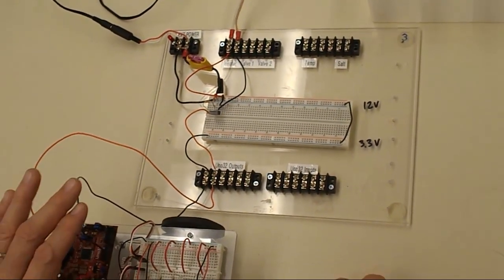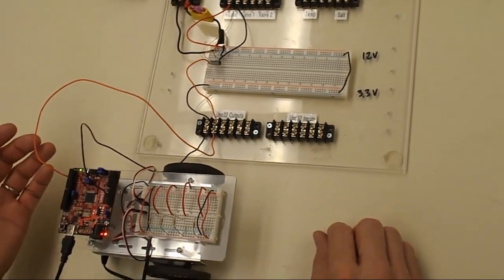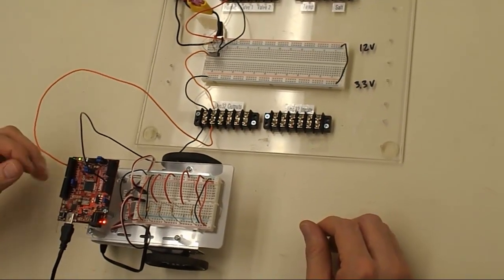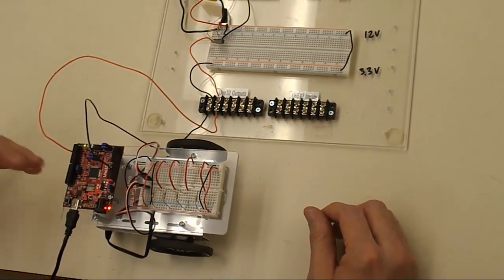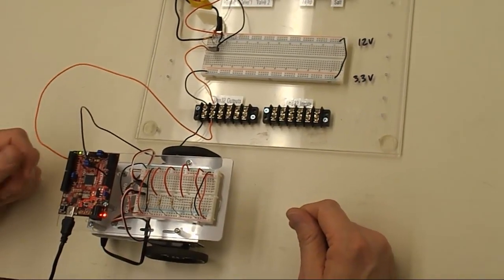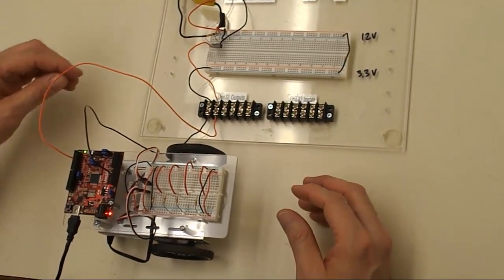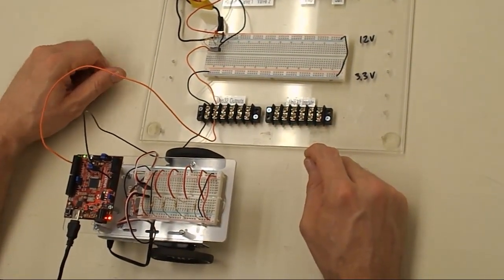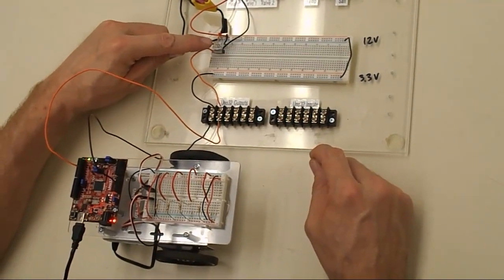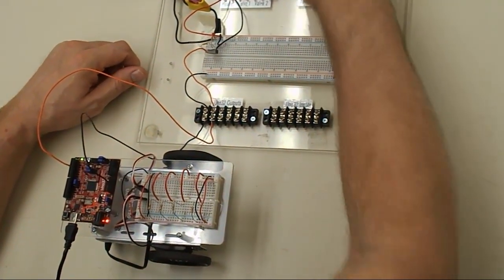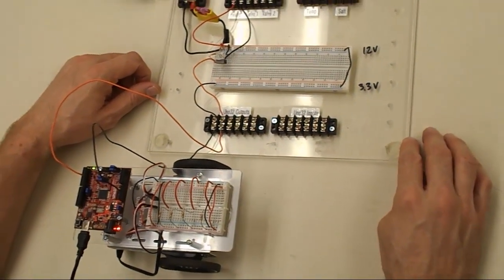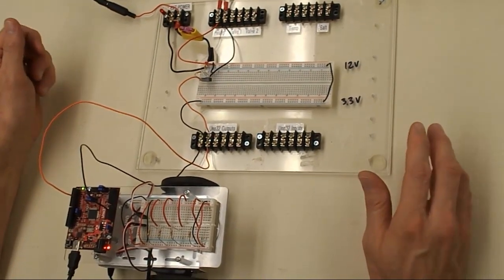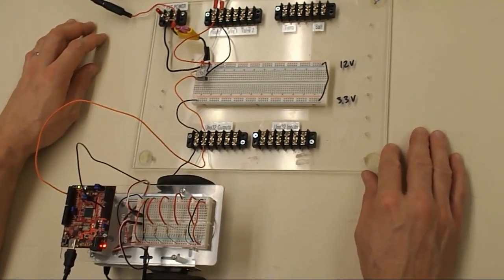So again, you'll need to program the Uno32. The base program that we provided tells you how to send the outputs low. You'll have to modify them to run them high and low for a certain amount of time so you can complete your measurements. Again, the tough part about this week is wiring this up and then taking the measurements necessary to find out both the current traveling through the base resistor and then the power going out to the different loads. So that brings us to the end of week 9. Make sure and get those measurements done during this week, and you should be all set to respond to questions and complete your PowerPoint.